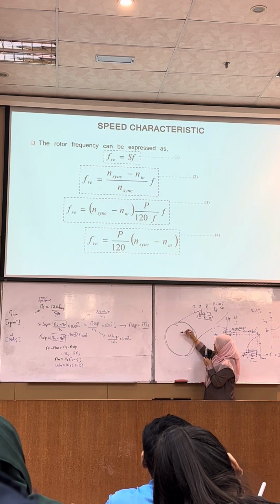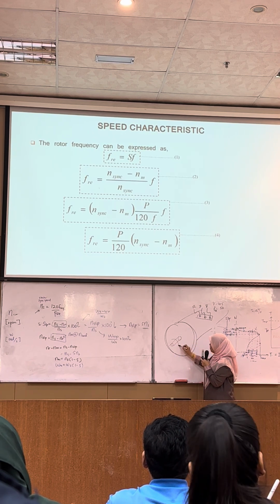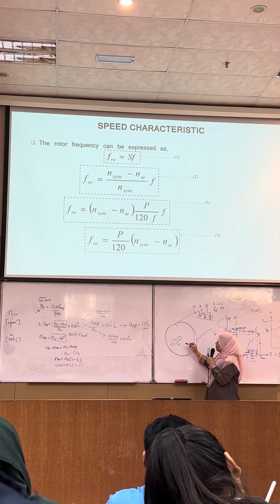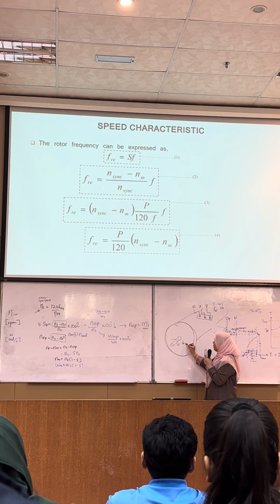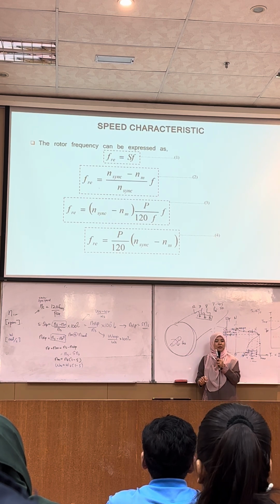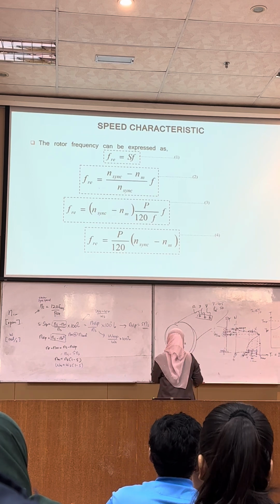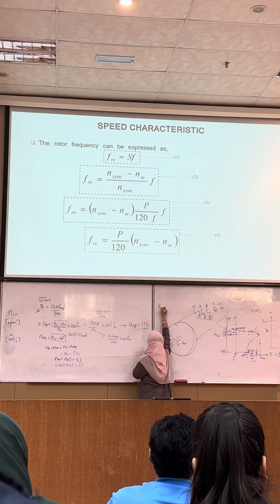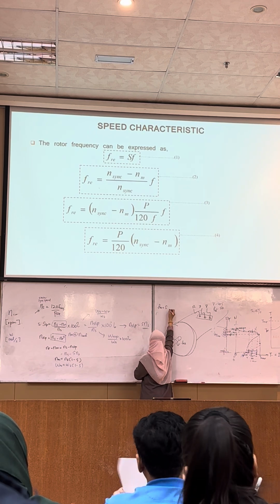So when the stator is energizing the rotor and your rotor started to move, rotor it has its own speed and also its own frequency. So the rotor frequency is slip multiply with stator frequency.